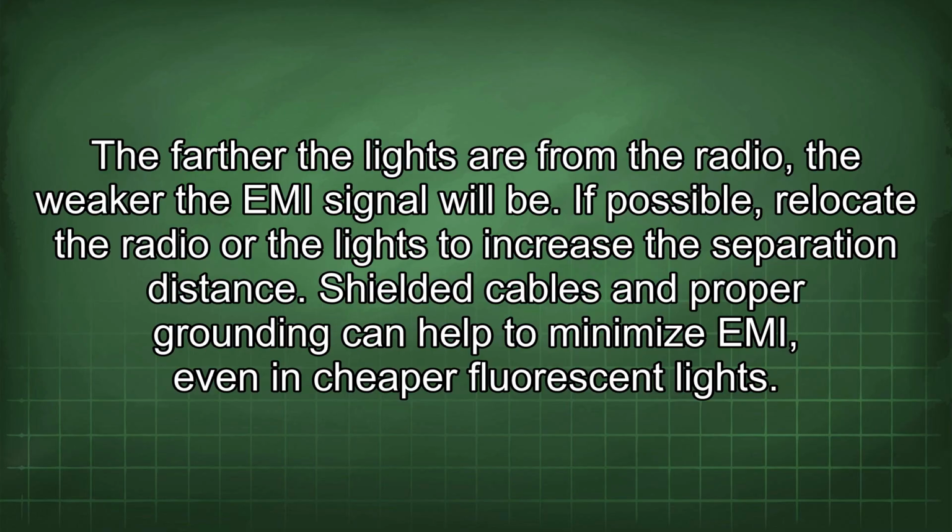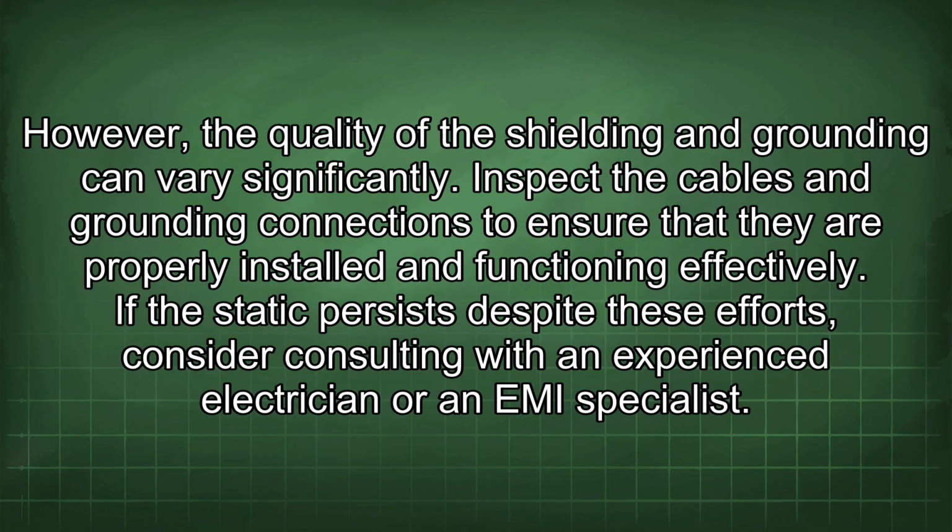Shielded cables and proper grounding can help to minimize EMI even in cheaper fluorescent lights. However, the quality of the shielding and grounding can vary significantly. Inspect the cables and grounding connections to ensure that they are properly installed and functioning effectively.